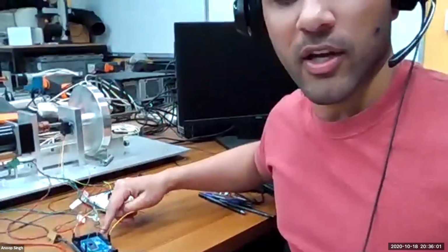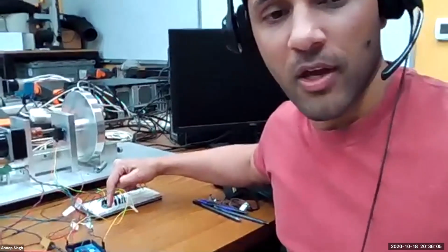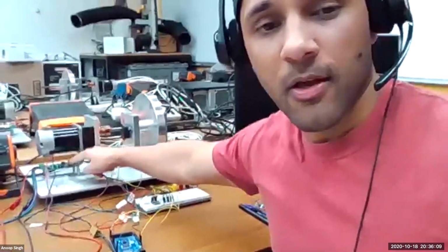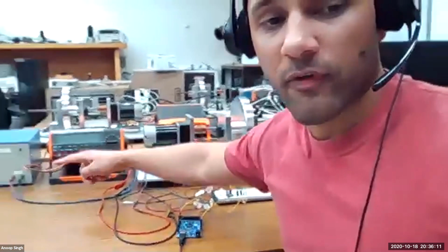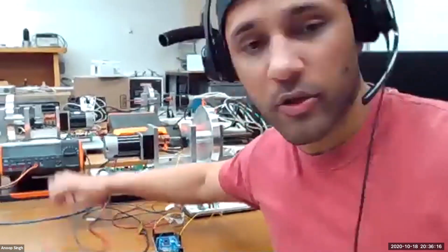So Arduino is going to give a signal to the DAC over here, the digital to analog converter, which is going to give the signal to the motor controller board over here. Motor controller board is going to provide a fraction of the 24-volt supply to the motor through these wires over here. Okay. Now let me share my screen to go over the two experiments.